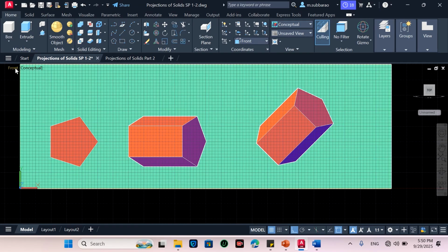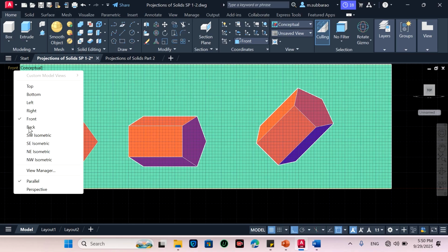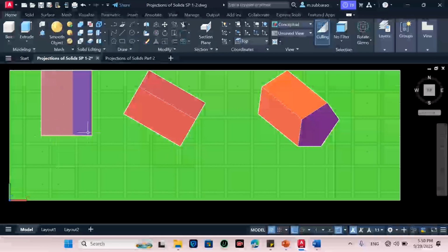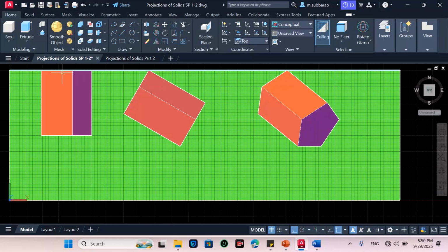And if I see the top view of these diagrams, the top view will look like this. So this is the top view, because the base is resting here, and in this second position the base corner is resting, and this is view 2. View 3 is just rotating view 2, and it is resting on its base corner.